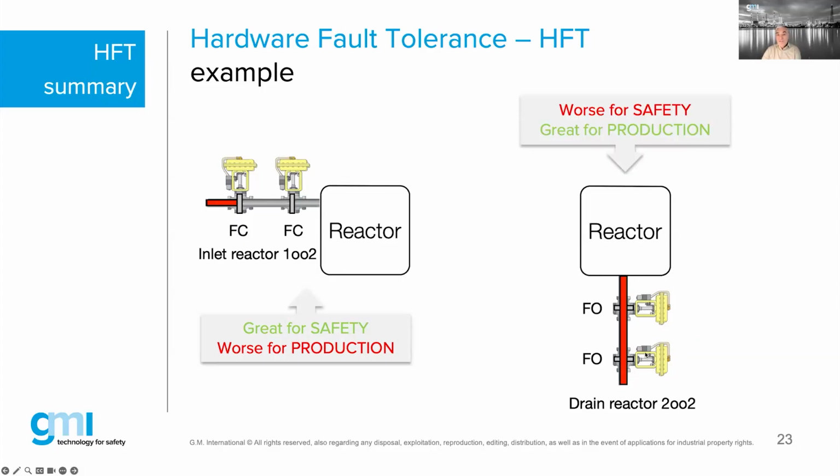Why? Because if one valve is leaking, they're not losing production. We as safety people, we hate that. 2 out of 2s for safety, we typically said forget it. Because if this valve is stuck closed, I can put 10 valves below here, and I can never drain anymore.